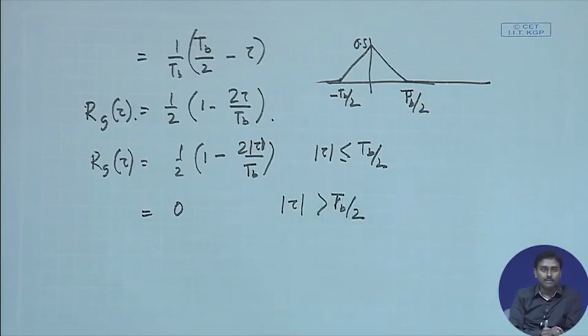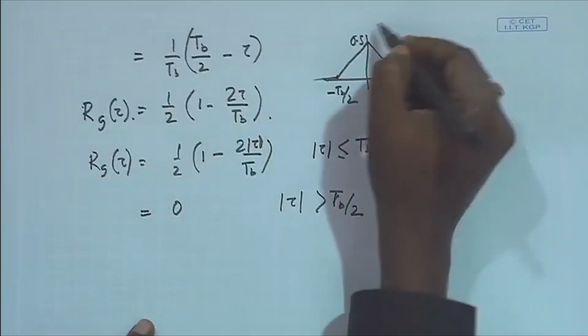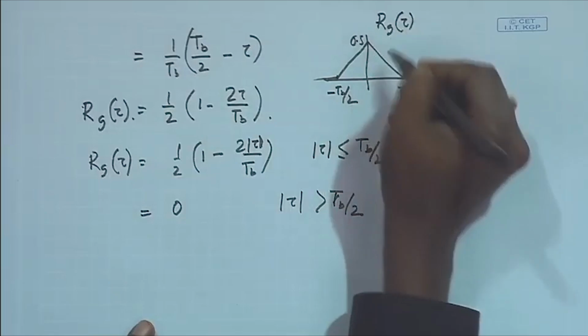Is this clear? This is pretty clear because the statistical definition of the signal was already given earlier. Though the signal was not deterministic, this time I could evaluate the autocorrelation because of the statistical definition of the signal that has been given. So from there I immediately get a time autocorrelation function, Rg tau. Now, this is a deterministic signal, and now I can do the Fourier transform.